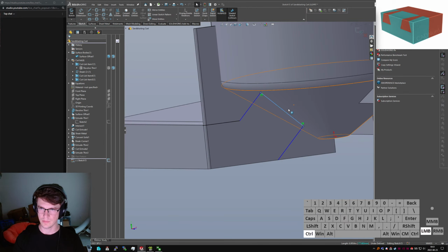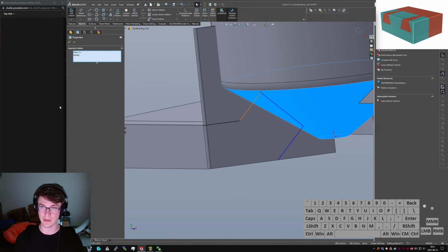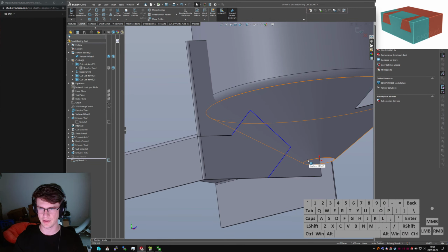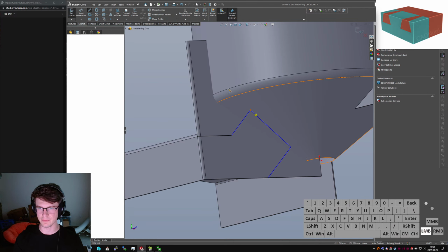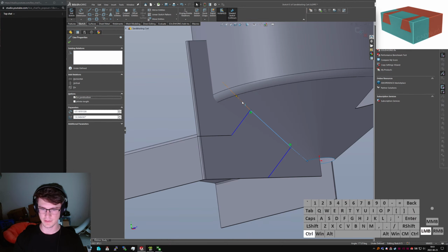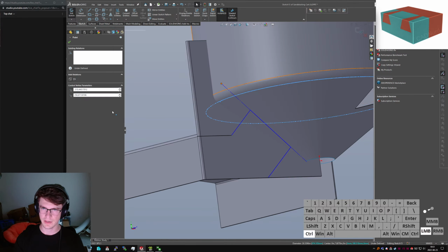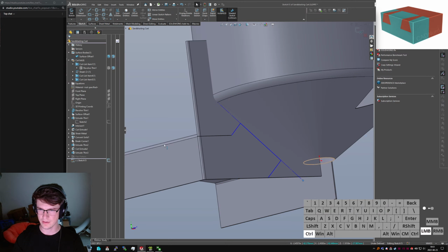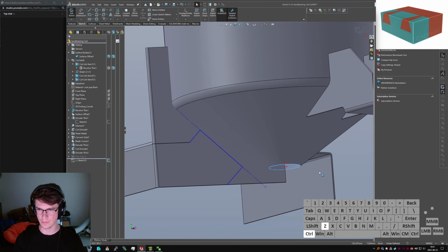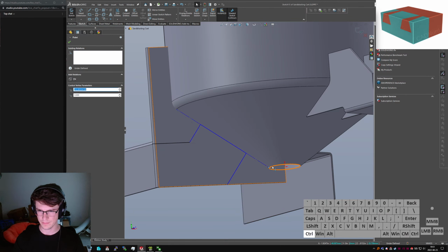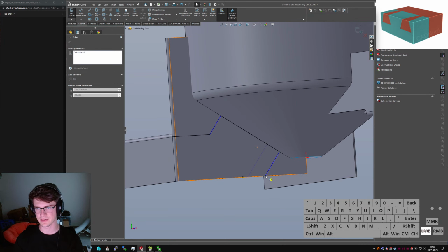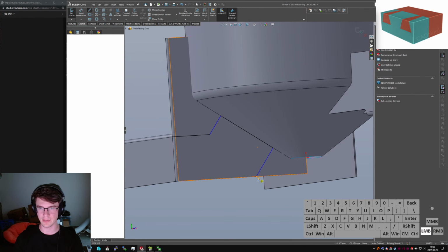So, we can pick this guy and say, or better yet, we can pick this. Oh, is it not going to let me put that on the surface? Oh, that's quite rude. Come on now. Well, there's workarounds for that, fortunately. We can add 2 construction lines. Make all of these collinear. Pick that, that sort of round point where I want my endpoint to be. Pick it down here. Give myself an endpoint. Pierce it in 2 places, and now I have a defined cut that will always end where I want it.